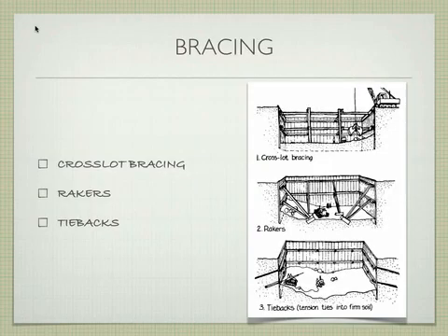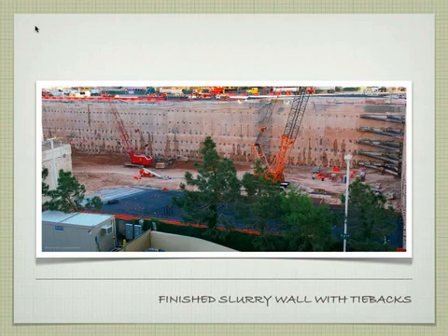So that was under the earth at one time? This whole piece was all under the earth, and so they got rid of that. The slurry walls don't necessarily have to go underneath the excavation because they're tied back, correct? Correct. They tend to go a little bit further than where your excavation would be, so that you don't get any undermining of the soil. So they're always going to go a little bit further, but the tiebacks are going to keep it in place, so it's not going to either overturn or undermine. That's the concept of it.